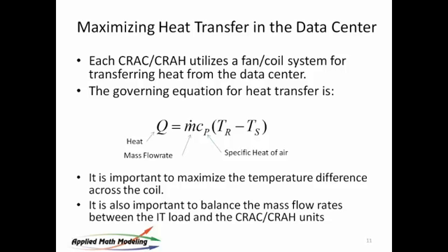And the typical delta T's that you see for IT equipment are 20 degrees. Now, they've gotten a little higher. Most recently, you see them as well at 30 degrees. But generally, we use a delta T of 20 as a way to get into the park.